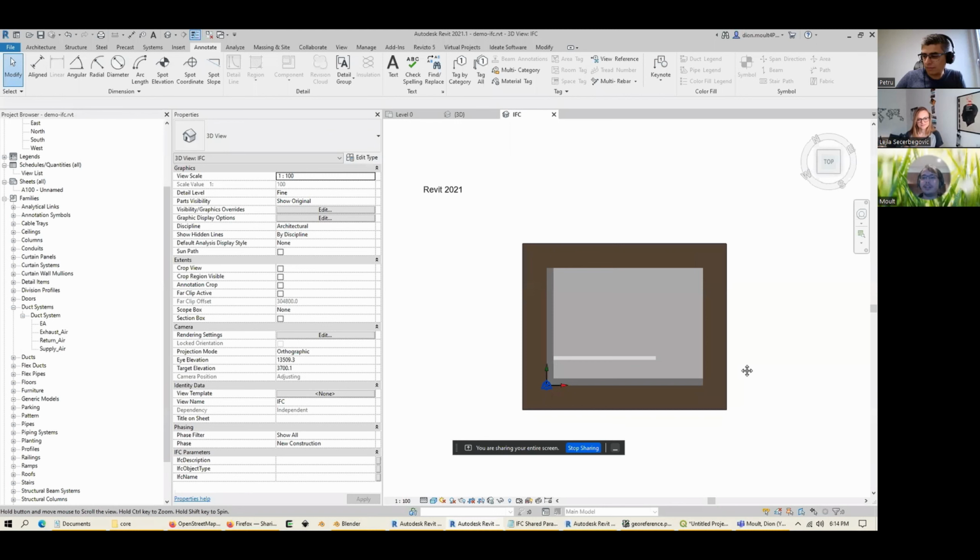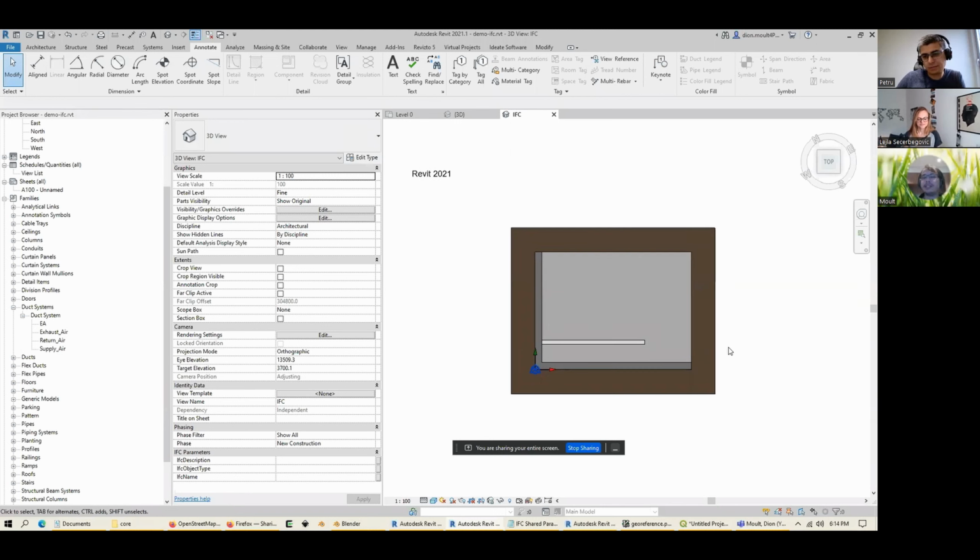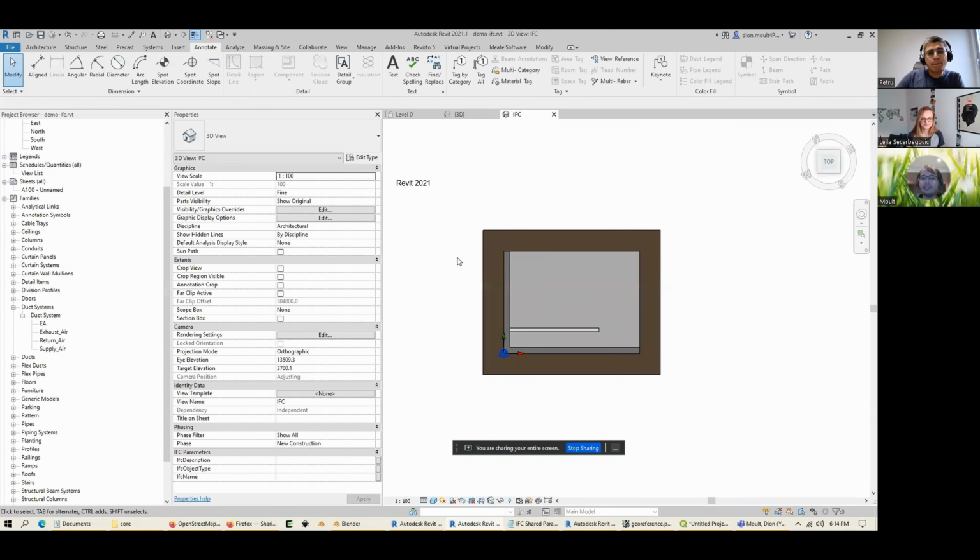And the moment somebody presses the link WG in Revit and just tosses that in, he has already made a mistake, because he's assuming that that's local engineering. He doesn't realize very often that it's eastings and northings, and it's not the same as XY meter measurements. And unfortunately, this project setup and checking of set out sometimes in architectural firms can happen in people who aren't trained in this stuff.